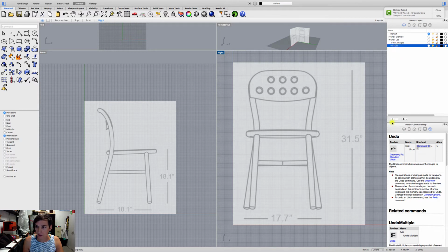And then I'm also going to make a new layer, create new sublayer. I'm going to do one for the back leg, and then one for the front leg. The reason I'm trying to break these up is because there can be a lot of information ending up in this workspace, and sometimes I might need to turn them off. It's very helpful to do that. Then I'm going to move this reference geometry, not into that layer, into the chair layer as a sublayer. Let's see, I just want to move this up. There we go. So I'm going to start working in the back layer.